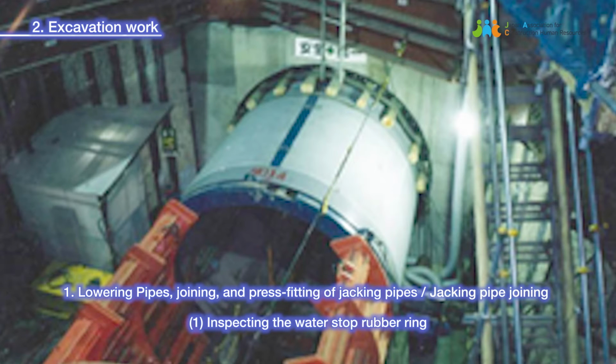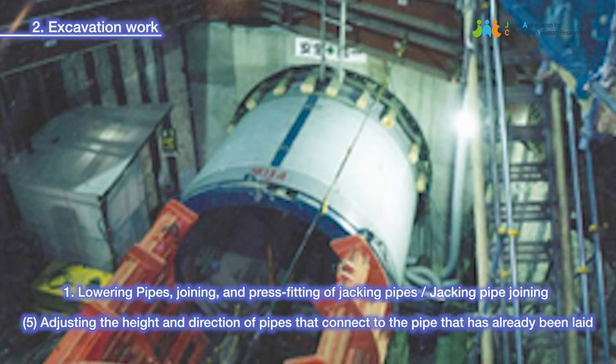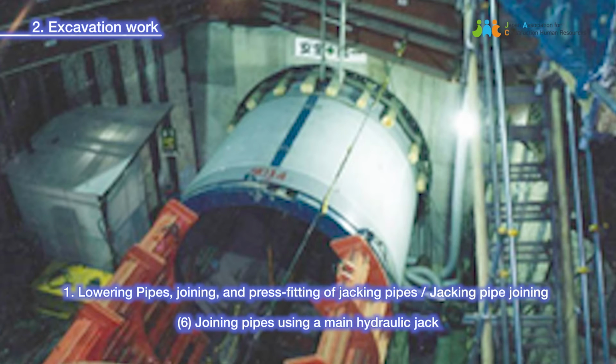1. Inspecting the water stop rubber ring. 2. Lowering pipes, jointly with people on ground level. 3. Applying bonding lubricant. 4. Connection and replacement of cables, excavator power supply, operation cable, tunnel light cables, etc., piping, lubricant material, ventilation, etc. 5. Adjusting the height and direction of pipes that connect to the pipe that has already been laid. 6. Joining pipes using a main hydraulic jack.